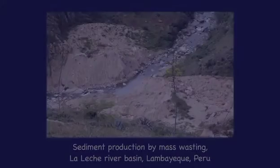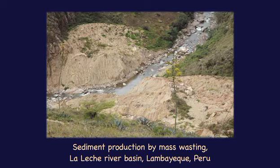and magnesium. The addition of water to many of the minerals present in igneous rocks results in the formation of clay minerals such as aluminum silicates. Oxidation is accelerated by the presence of moisture in the air. Oxygen combines with other elements to form sulfates, carbonates, and nitrates, most of which are relatively soluble. Sediment is also generated by slides and mass wasting in steep slopes under the action of rain and gravity.